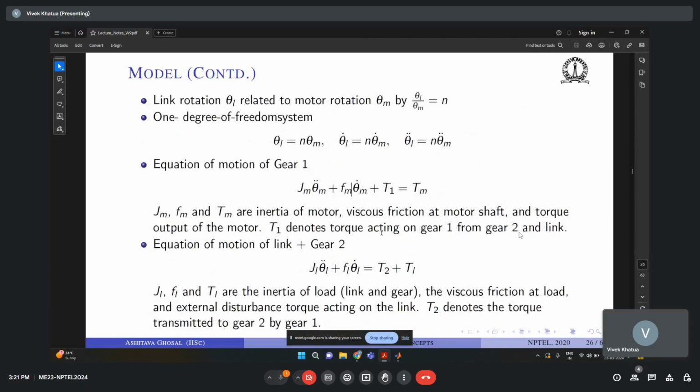That is using feedback. That we will come back to later, the physical systems that are involved in getting you the feedback. The equation of motion for a single link, or let's say even for a robot, has to be transformed from our link rotation to the rotation of the motor, right?